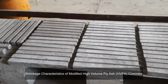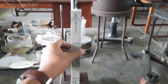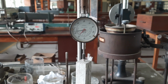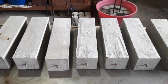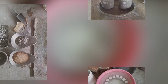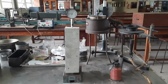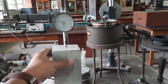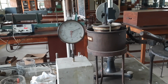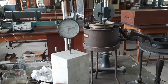This study examines the shrinkage behavior of modified high-volume fly ash, HVFA, concrete modified by in-situ grown CSH, using slag as a sustainable alternative to conventional mixes. The research investigates how fly ash, slag content, curing, and environmental conditions impact compressive strength and shrinkage. The findings indicate that HVFA mixes with slag enhance early-age strength while keeping shrinkage within acceptable limits, and emphasize the need for optimized mix designs and shrinkage-reducing additives to improve performance.